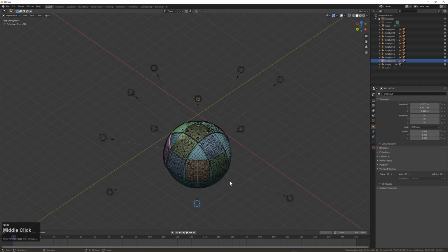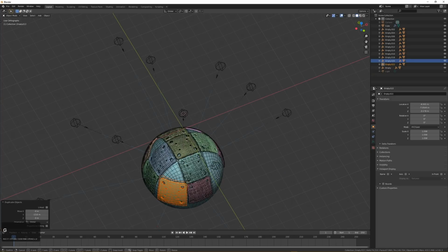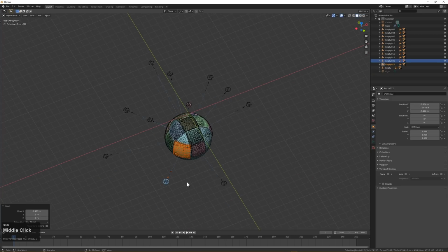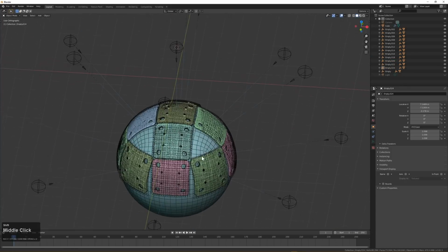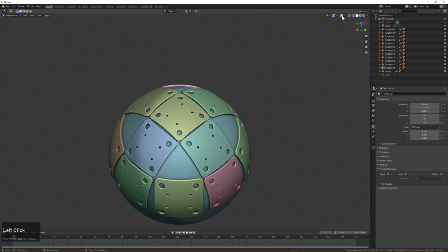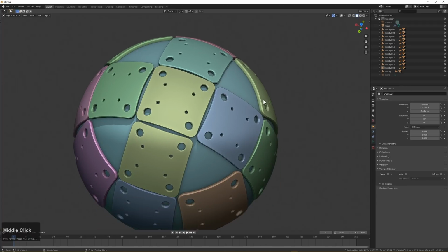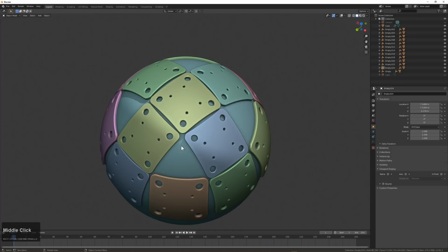So we'll press Shift G, select children, select this. And we'll duplicate one more time, just cut out the middleman. Usually in these workflows, as I do things over and over, I'll eventually start cutting out steps until things start making more sense. If we turn off render overlays, you can see what we got here for this example. Keep in mind that this was made from just a plane dealing with a curve, and then all of a sudden at the end we have this thing deforming around a polysphere that we added. So with that, we'll wrap this thing up.